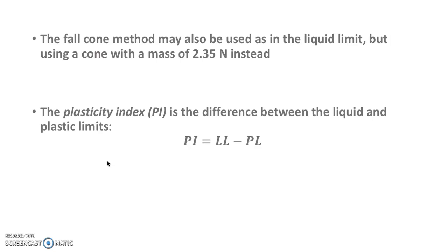Plastic collapse takes place when the structure is converted into a mechanism by the development of a suitable number and disposition of plastic hinges. So the plastic collapse factor represents one of the most important outcomes of a plastic structural analysis, and it is useful for the reliable and economically safe assessment and design of a ductile structure. So basically, that's the importance of the plastic limit.